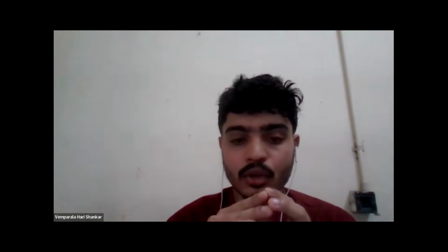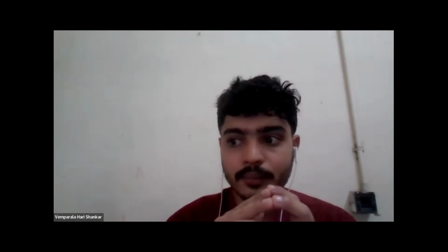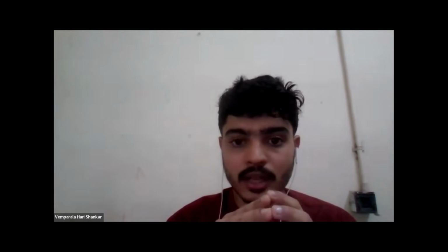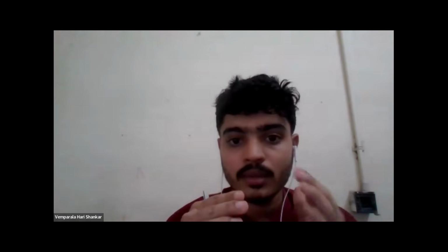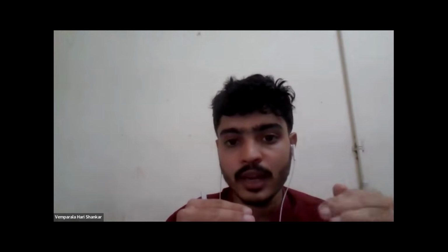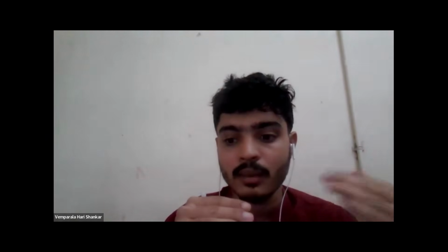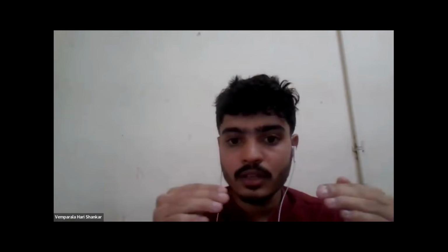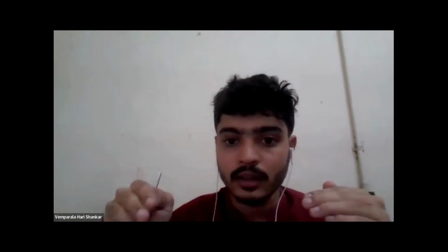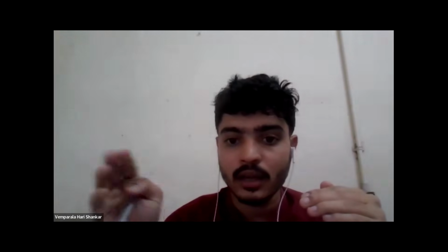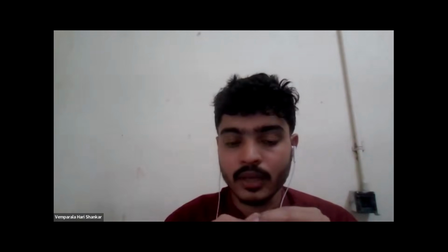But if we consider fork join, initially a is 1, and after 5 nanoseconds, a is 0. And here the main difference comes. In initial begin, after 10 nanoseconds, I want my data to be high, it will come out like that. But when it comes to fork join, again at 5 nanoseconds itself, a should be 0 or 1 according to what we have given.